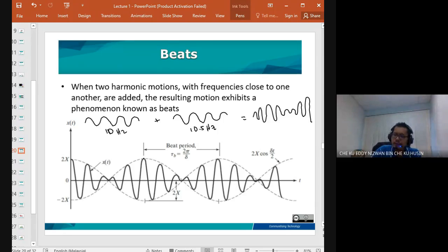Actually, in vibration measurement, if you want to measure the vibration intensity, the common practice is to measure only a few seconds, around 2 to 4 seconds, and then state the reading. So the problem is you can misinterpret the data. When you do the measurement at this period, you can declare this is low vibration because you take a sample at this point, which can give the wrong interpretation, but actually it can reach up to this level.